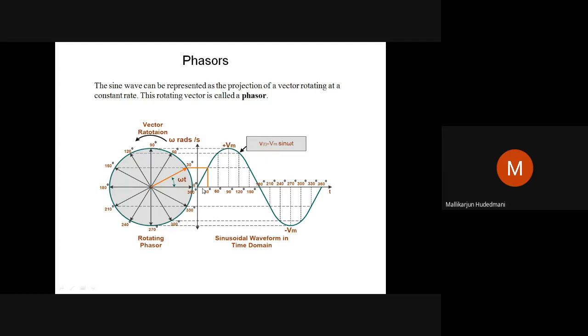So this wave is represented as a magnitude, the peak value appearing in the wave, lying horizontally at the origin point, and as the wave progresses forward, this vector starts rotating in the anti-clockwise fashion. You can see when I move 30° forward and stop, the vector representing this quantity, magnitude Vm, which was lying here, has to take a shift of 30°.